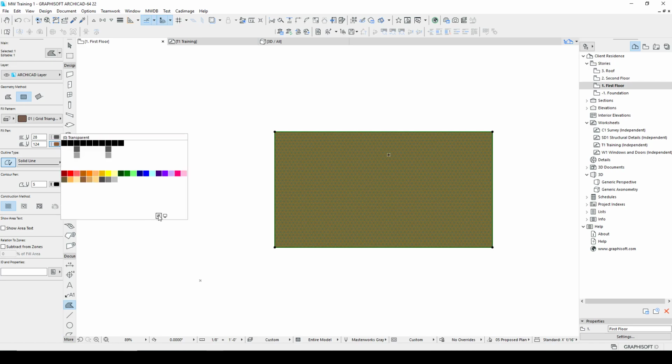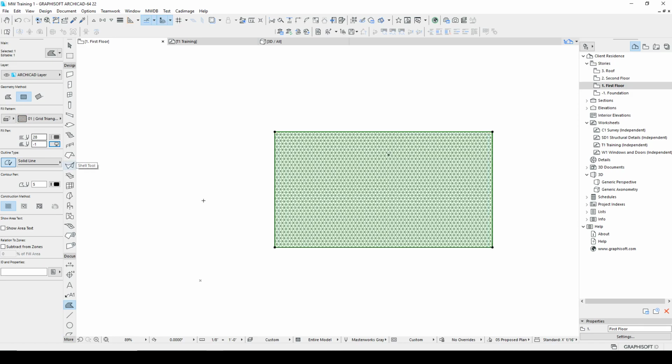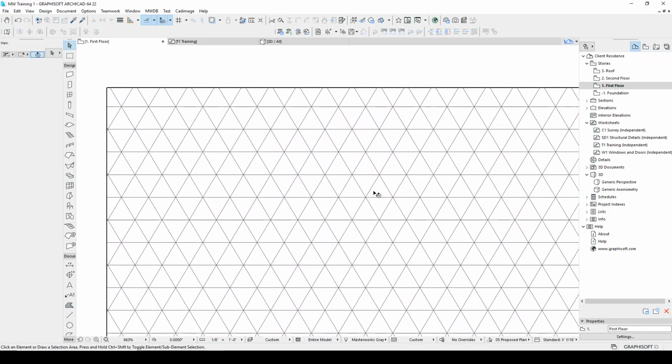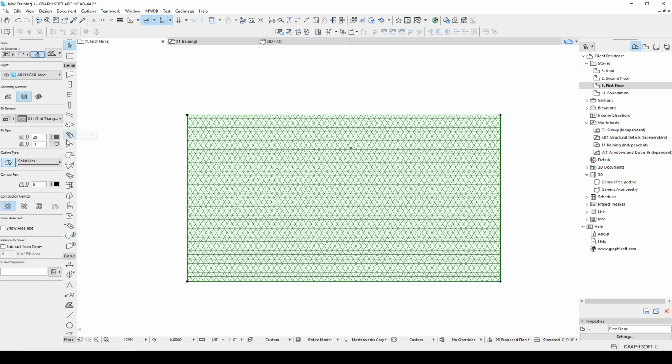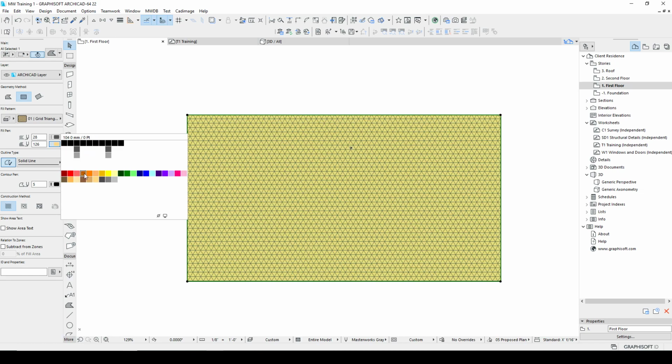The background color, one important feature here is we have the no fill and we have the screen fill. So the screen fill means that the background will take on the color of the screen, and that's generally the one you're going to want to use. And so you can see here we have the vector shape of these triangles over the top, but nothing in the background. And if we change the background color, it would just assume that same color. Whereas if it was an empty fill on a colored background, we'd end up getting probably a white. So I'll put this back to a colored background, and that's really why I have these colors, just so that these visually make sense and represent whatever element you're drawing.